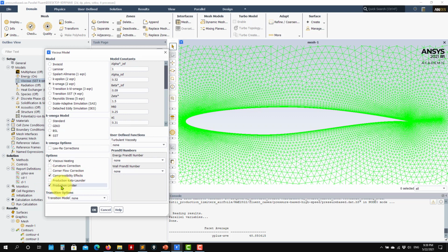By the way, if you enable this, once you go here to the bottom, you have this clip factor. This is the one that you use to control that limiter. Usually the default value is 10. If you put it to 0, you are disabling that limiter. 10, you use the default values, and you increase it, and you are adding less limited, let's say, yes, less limited.